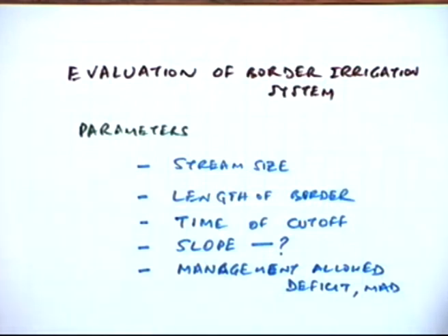Since when to irrigate is entirely dependent on a decision which can be made by the management, whether it is the farmer or the irrigation department, if it is dependent on the supplies. So how these different parameters, the advance and the recession curves, vary when you decide to irrigate at different moisture content levels can also be evaluated.